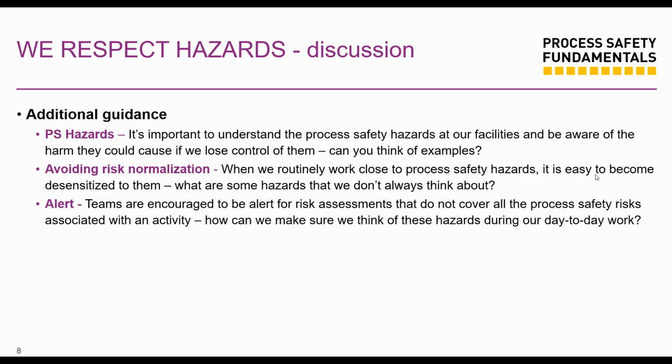So it's easy to become desensitized to these hazards. So when you're starting a task, do a risk assessment, a hazard assessment, and think of stuff that people don't normally think about and that could go wrong, and put controls in place. So your teams are supposed to be alert for risk assessments that do not cover all the process safety risks. And how can we make sure that these hazards during our day-to-day work are eliminated? So that's the first one.